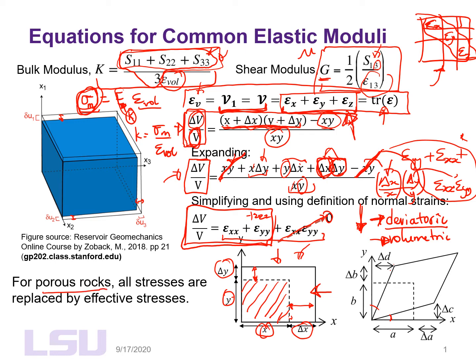For porous rocks, which are saturated by fluids, we don't use stresses. We don't use total stresses. We use what? The effective stresses, right? The part of the stress that acts on the grains, on the pore structure.